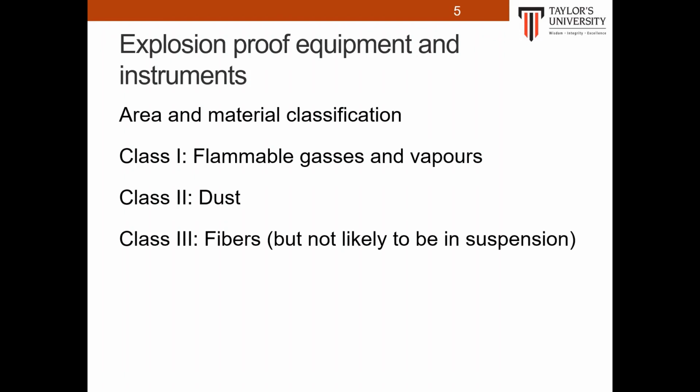Most safety practices for electrical installations are based on the National Electrical Code (NEC). Although states or insurance companies may have their own installation requirements, they are usually based on the NEC. Process areas are divided into two major types of environment, the XP and the non-XP.